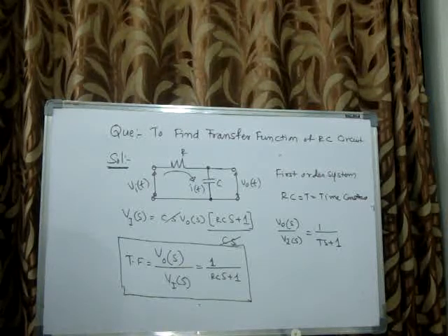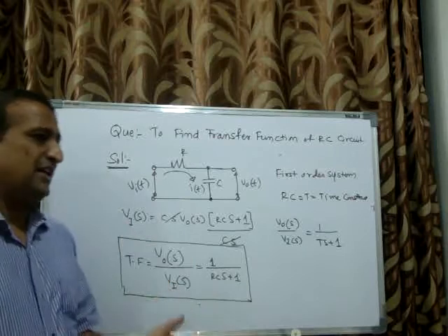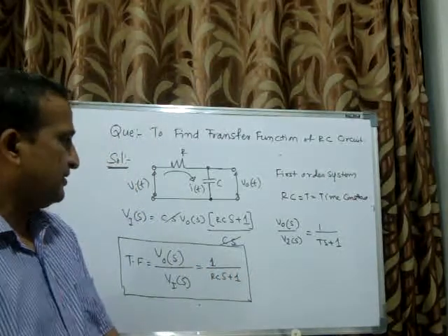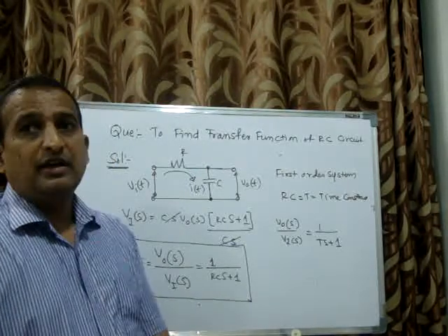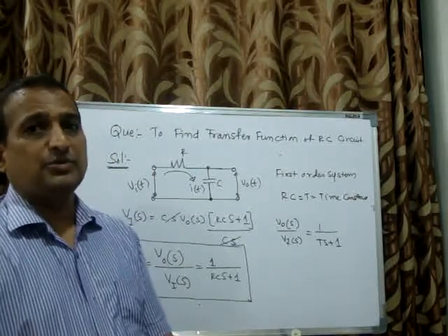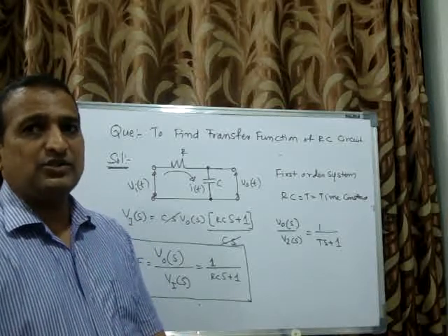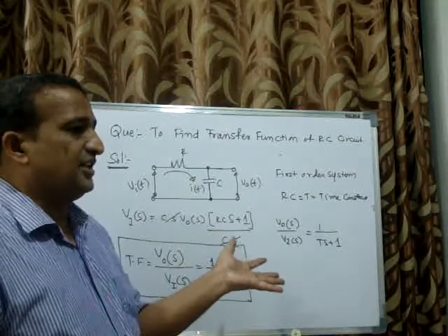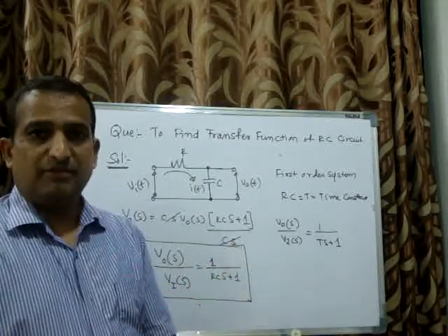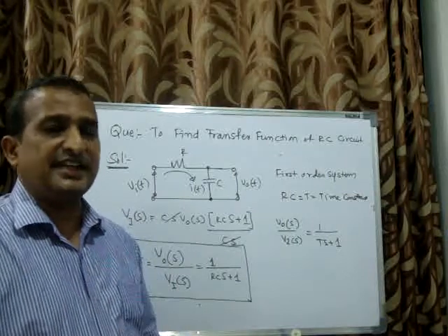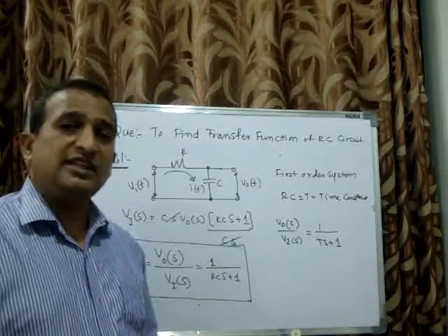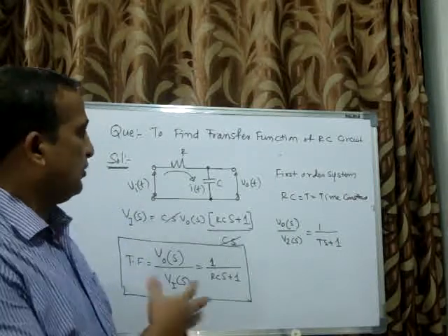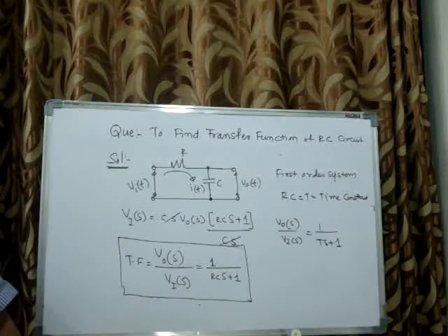Like this, we'll come to know what the use of Laplace is, how we have to apply the Laplace, and how to find a transfer function. Without Laplace, we cannot find a transfer function. And once we know the transfer function, its use is to find the time response. Time response is very important. At the first second, what is the output? Second second, what is the output? Third second? Fourth second? We'll find. So this is one good, basic example of an RC circuit.